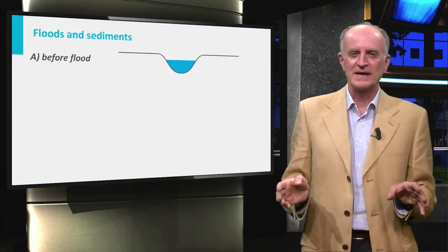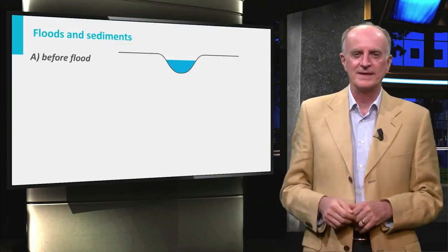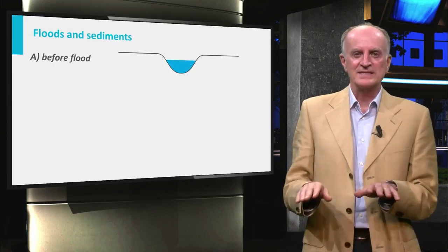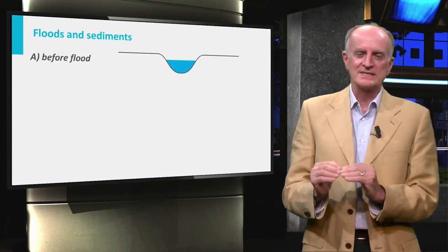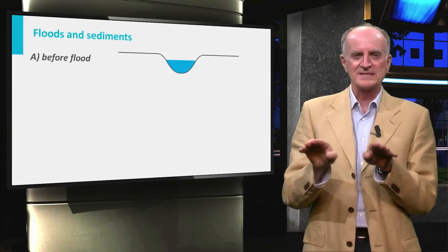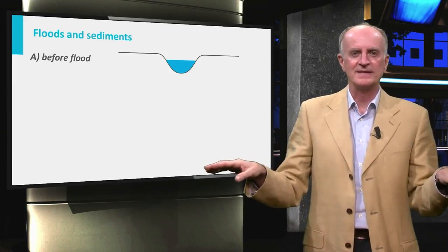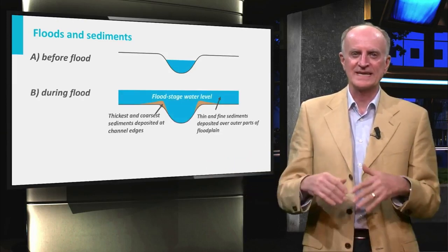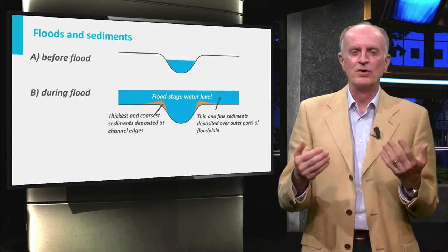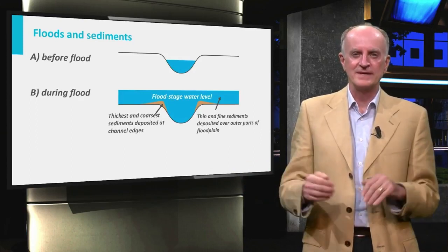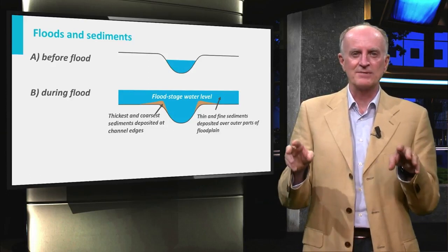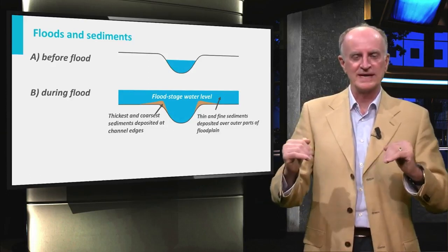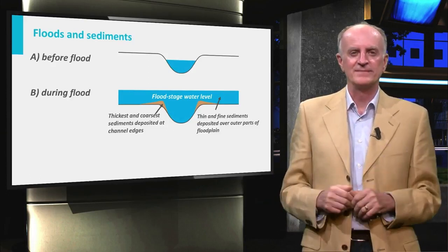And here you see what happens during and after the flood. As valleys and the large plains have low depths, the river level will rise with the flood, and waters will pass the river banks and invade the floodplains. As soon as the waters get out of the riverbed, the flow velocity will dramatically decrease, and the sandy sediments they were carrying are dumped, forming natural dikes, which we call levees.